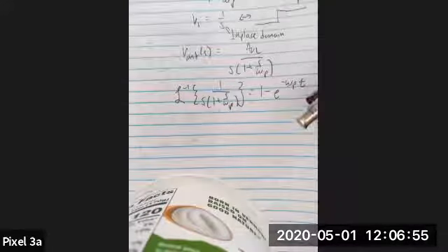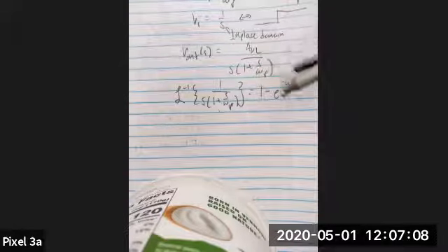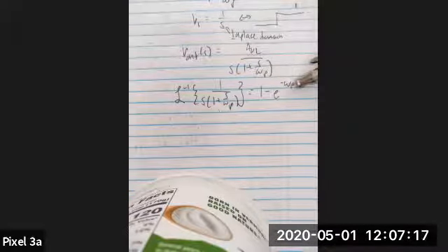And so this is what we call the single pole settling, because we have one pole and a step. We see that the step's eventual final value is 1, and that's this 1 here, and then we have the settling of the pole where an exponential is gradually reaching this level of 1 as we go through time with this time constant 1 over omega p.